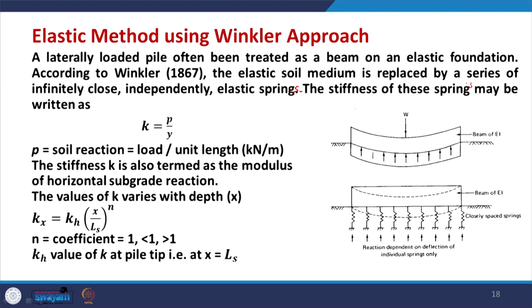What you have here is a pile, actually the pile is vertical, right? For understanding what we did, you can understand it like this. In this case, this was your pile and the soil provides support from both sides, but for the time being assume that the soil support is all around the pile and the whole support is represented on one side. So, we have one side soil and one side pile. The one-side soil support which you are considering represents the whole support all around the pile.